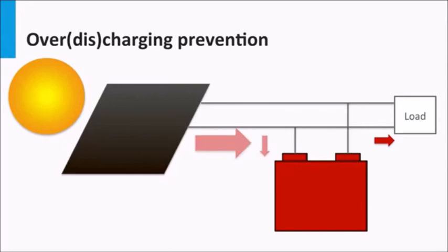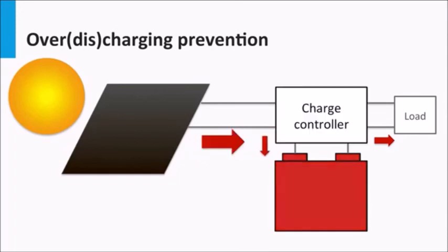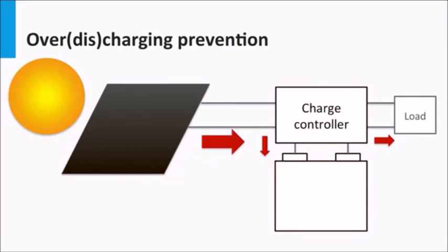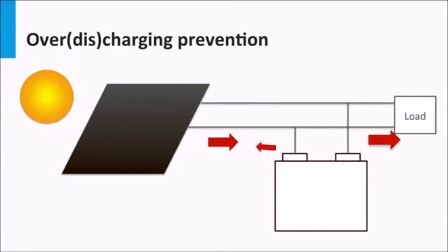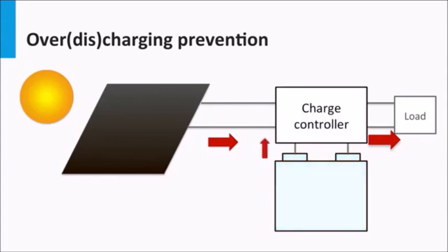This brings about its own set of problems like gas formation in the lead-acid battery, capacity loss, and overheating, to name a few. The charge controller here plays a vital role by cutting off the PV power from overcharging the battery. Similarly, in severe winters, when low irradiance causes the load demand to be more than the supply power, the battery is heavily drawn. The battery under such conditions tends to be over-discharged, which weighs strongly on the battery life as discussed in the previous block.